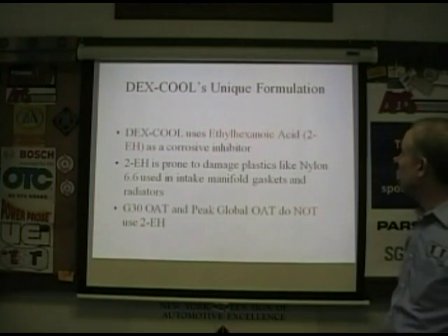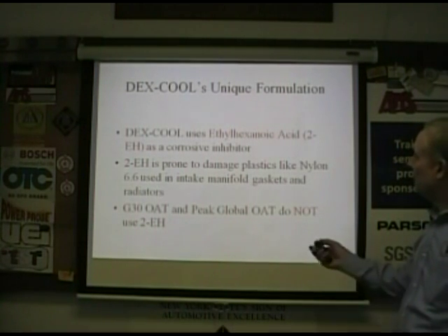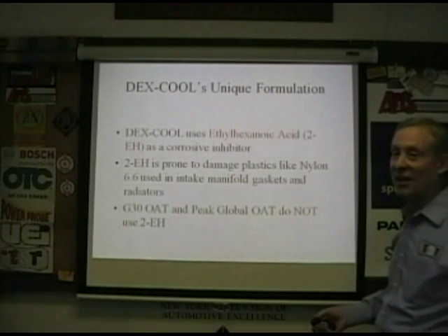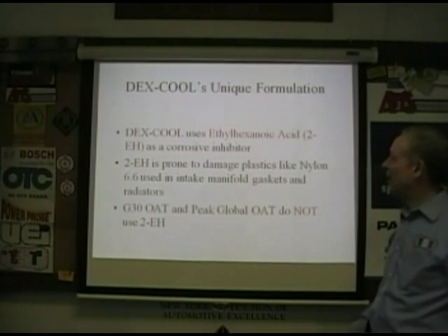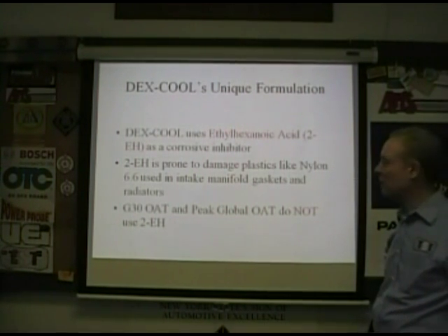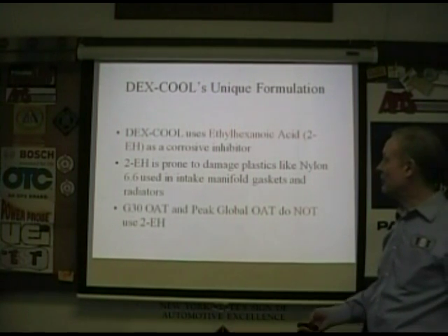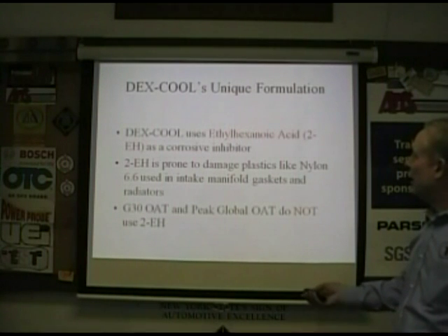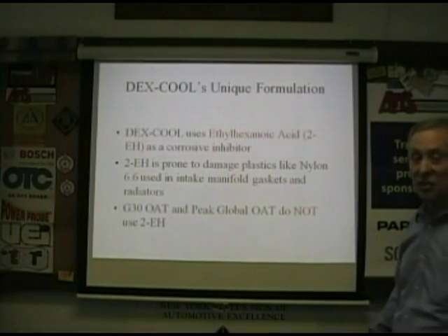Okay, Dexcool's unique formulation. I have trouble pronouncing this word, but it's an ethyl hexanoic acid. All right, that's what it's using as a corrosion inhibitor. Wow, that's a mouthful. It is a mouthful, and it's not compatible with other corrosion inhibitors. All right, it can damage plastics. So this is where you got to watch out.